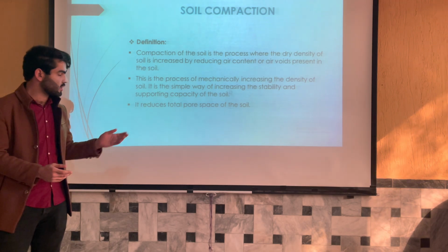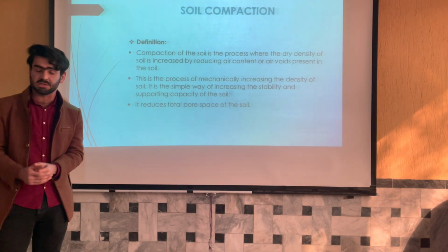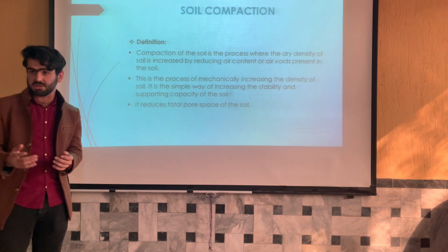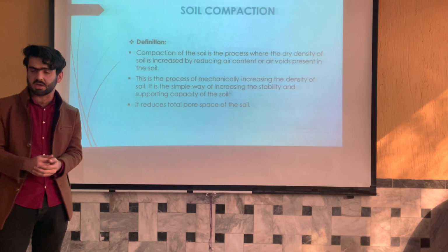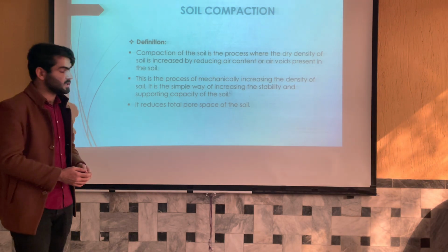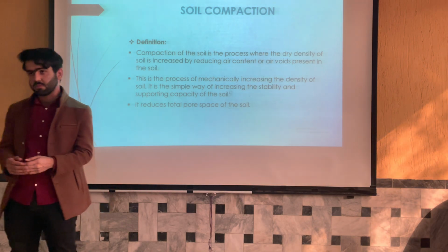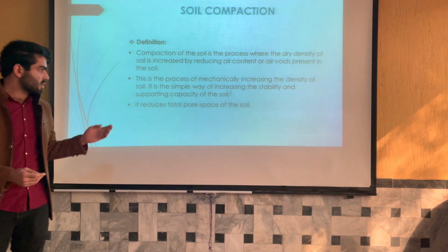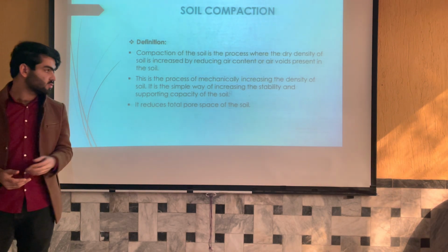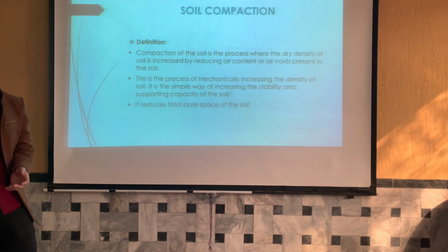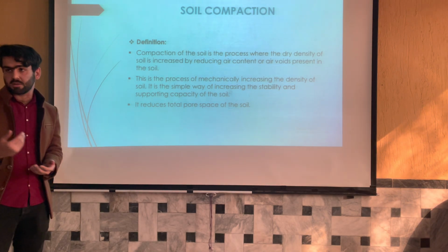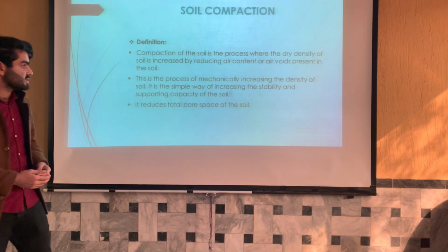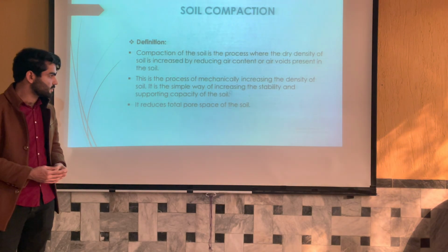Consolidation is also a process of increasing the density, but consolidation actually happens naturally, and it does not require any mechanical apparatus, but it does take a lot of time. So in most of our projects we use a mechanical apparatus to shorten the compaction process. It is a simple way of increasing the stability and supporting capacity of the soil.